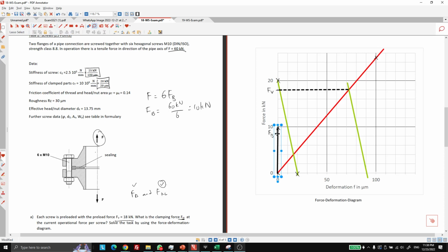This FB line has a 10 kilonewtons value, and this 10 kilonewtons has to fit in between the red and green lines. What you can do at home or in the exam is use a ruler and measure, and see, oh, it's like 43.2 millimeters. So you have to slowly measure, oh, how much is this? This is too much, 50 point something. So you have to adjust using your ruler. But for me, I will just copy and paste the same length and adjust accordingly.